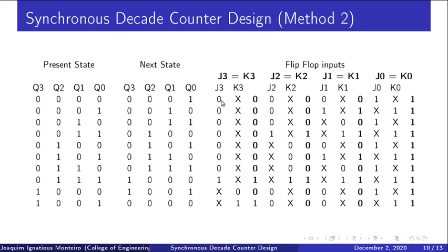What is done here is that I'll observe this K-map and fill out the columns which are drawn bold like this. Say I'll check this: 0 don't care is either 0 0 or 0 1, so that means it is 0. Just like we did for combinational logic design using a multiplexer, same pattern. 0 don't care is as good as 0, and 0 don't care, 0, same way. 1 don't care means that is 1.